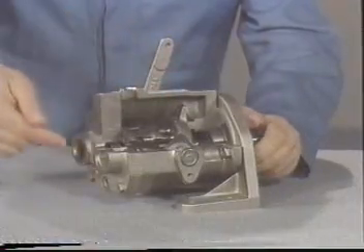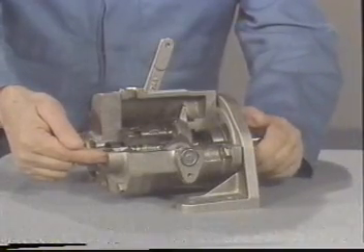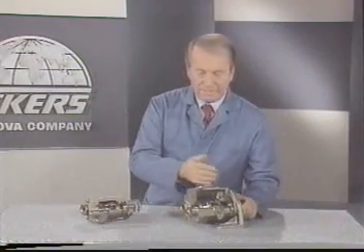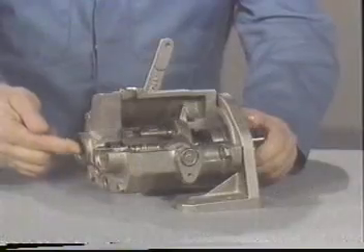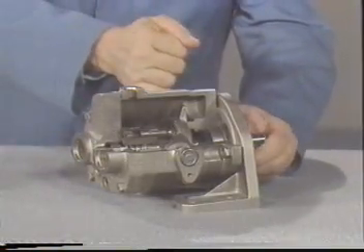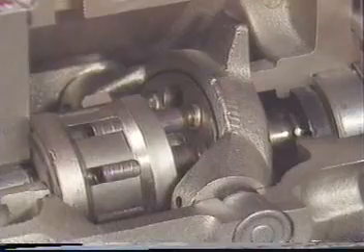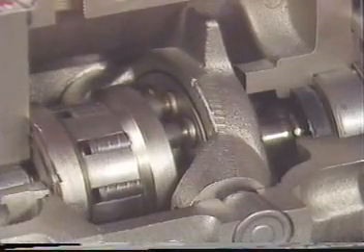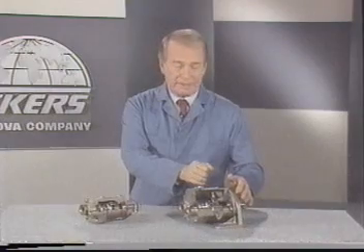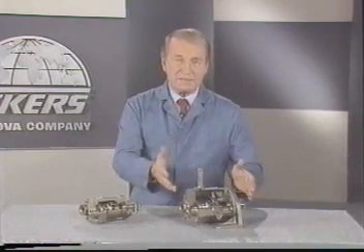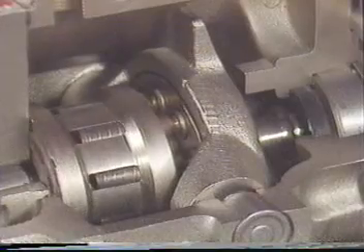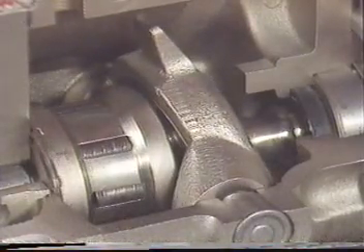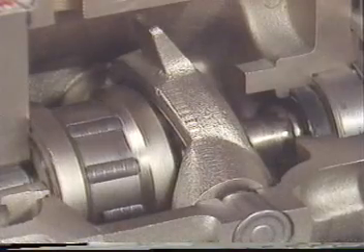As they come out, oil enters here, making this the inlet port. Pistons on the opposite side are being pushed in by the swash plate, and oil is forced out of this port. Notice how the piston movement is decreased as the lever is moved towards center. Centering the lever puts the yoke and the swash plate at right angles to the shaft, and the pistons cannot move in or out. Now, if we continue to rotate the drive shaft in the same direction, but move the lever across center, the piston movement and oil flow are reversed.